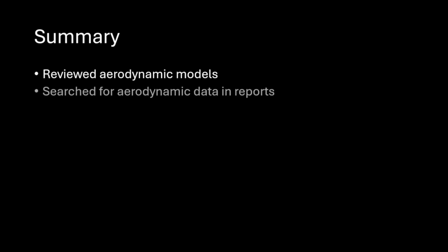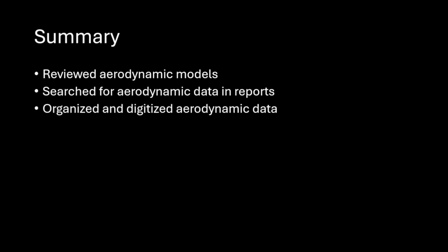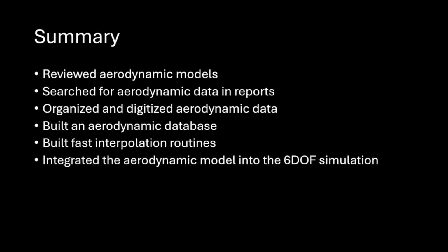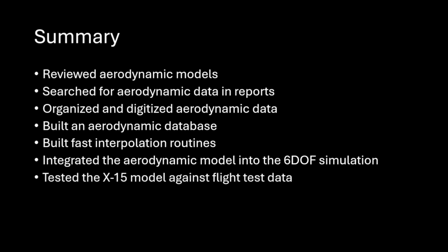In this lesson, we reviewed an aircraft aerodynamic model using the X-15 as an example. We searched for aerodynamic data in open reports, extracted plots, digitized the data, and organized it, subsequently processing that data into an aerodynamic database. This involved interpolators, and we explained custom fast interpolation routines developed for fast 6-DOF simulation. The aerodynamic model was integrated into the Python flight simulation and then evaluated against flight test data in the literature.